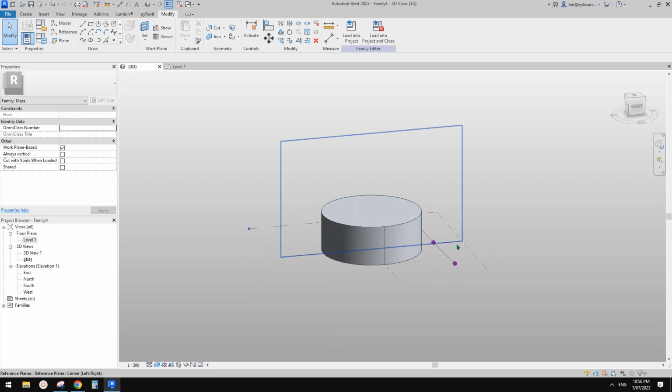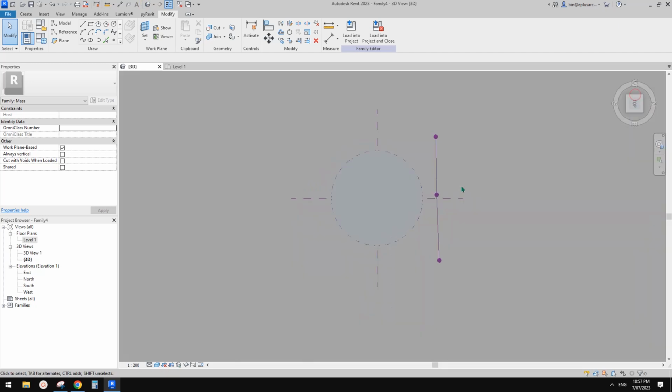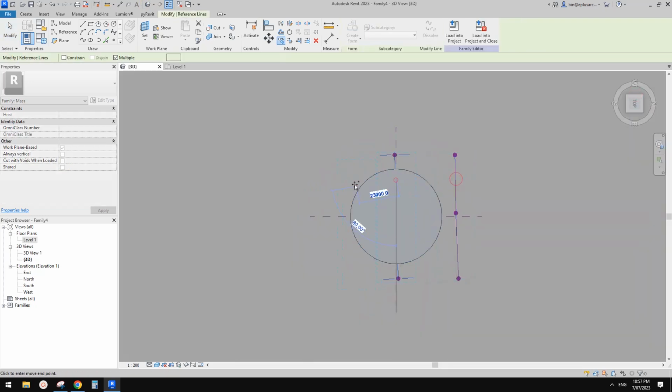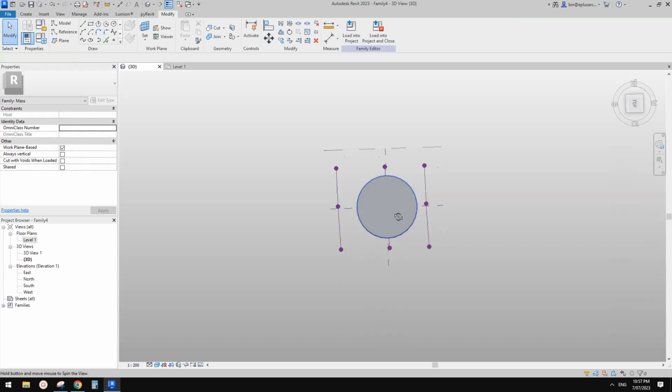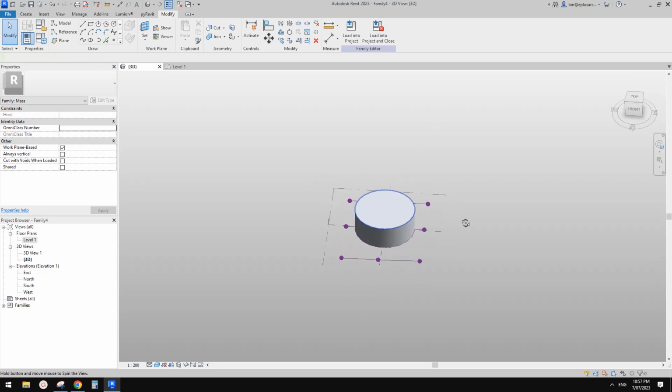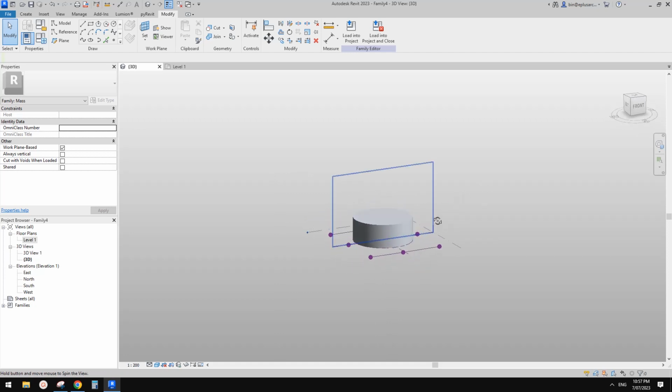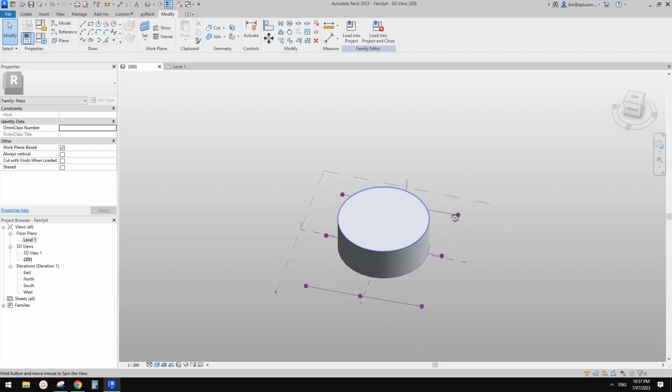Okay, so now let's go to the top. I'll just copy this 1, 2, 3, and then we create. Oh, we need to create a void, a solid, a void too, because we can't just create a surface, right? So we need a closed profile.